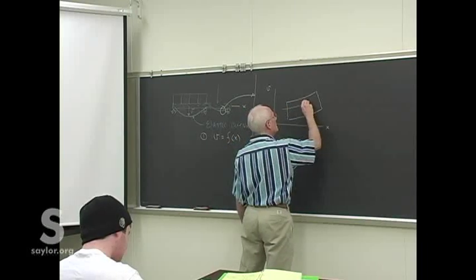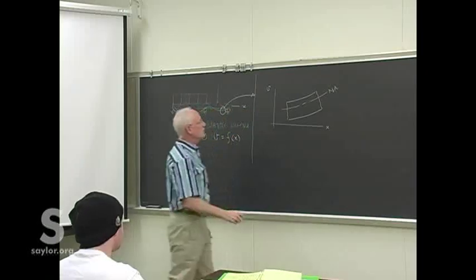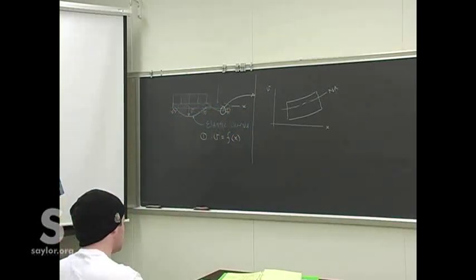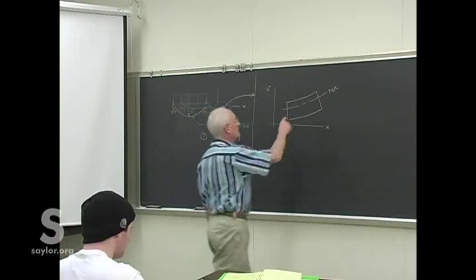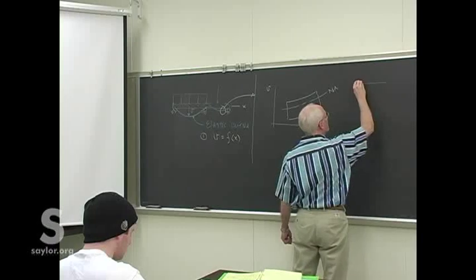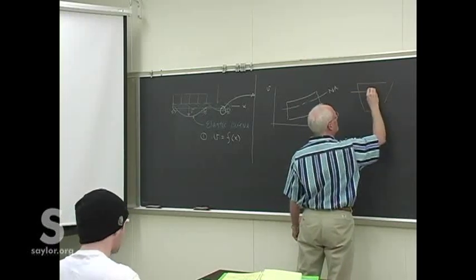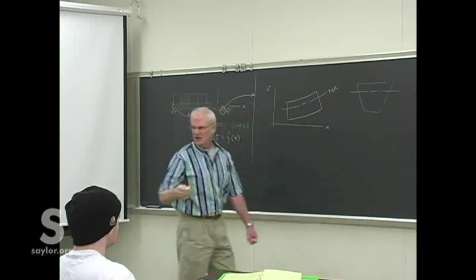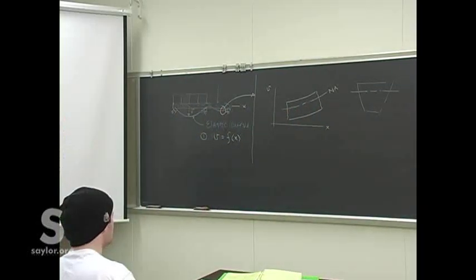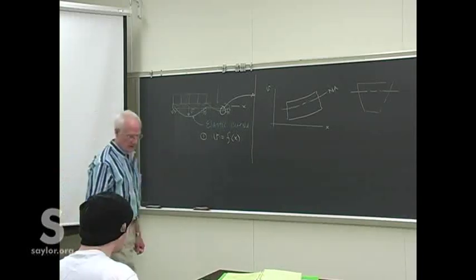We've got, of course, the neutral axis passing down the beam somewhere, depending upon the shape of that cross-section. If the neutral axis is up at the top, then it's a beam that's a bit wider at the top in cross-section than usual. That's not important yet. That just gives us a place from which to measure things.